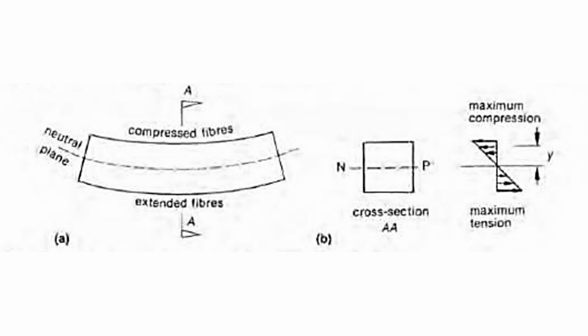One important difference between bending stress and some other types of stress considered previously is that, unlike direct tension or compression, bending stress is not distributed uniformly over the cross-sectional area of the beam. Every beam can be considered as being made up of a large number of horizontal layers or fibers held together by the internal adhesion between them. When a beam is subjected to bending, the fibers of the convex side are extended, while those on the concave side are compressed, as shown in the figure.